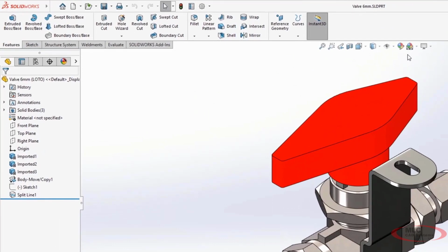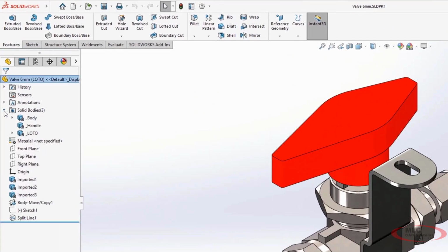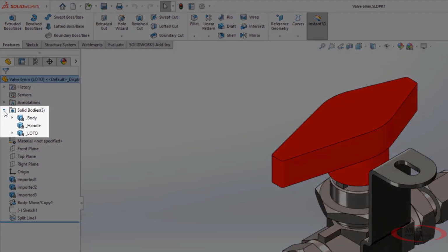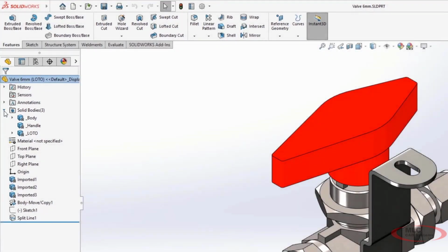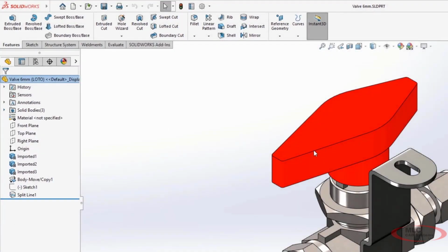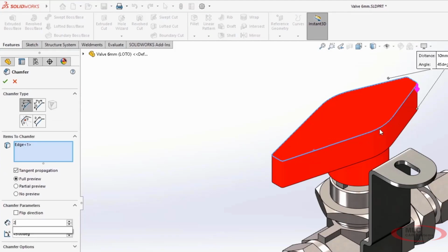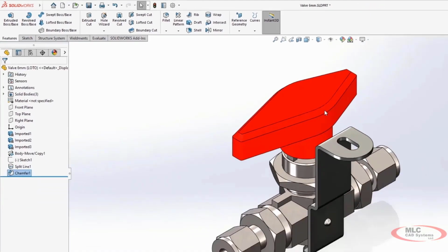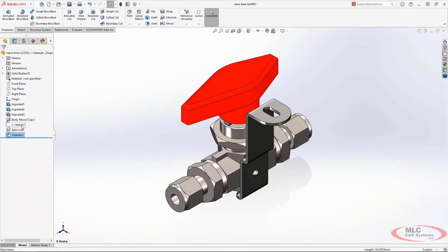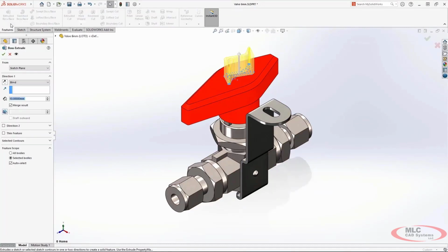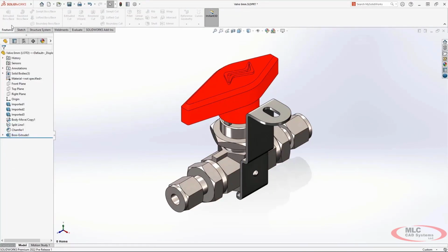The supplier had originally provided their files in a mesh BREP format. SOLIDWORKS 2022 introduces new hybrid modeling capabilities, which is going to allow us to work with these file types as if they were native SOLIDWORKS files. Adding features such as chamfers, extrudes, reference planes no longer require intermediate bodies or Boolean operations.